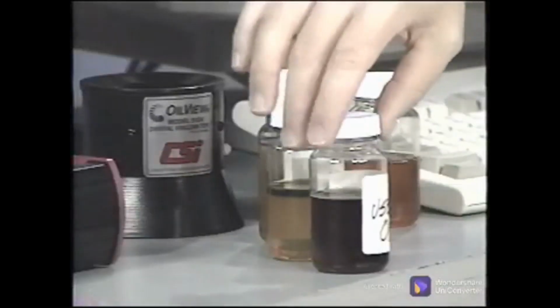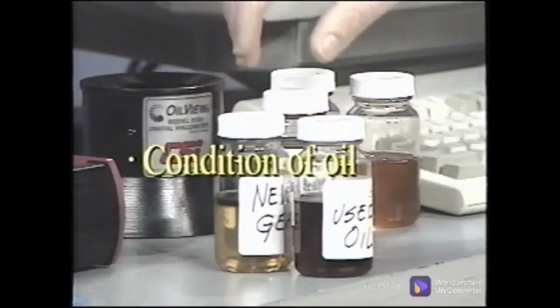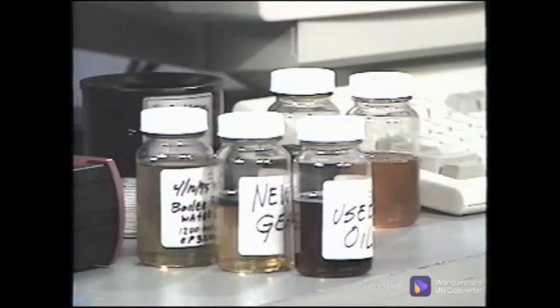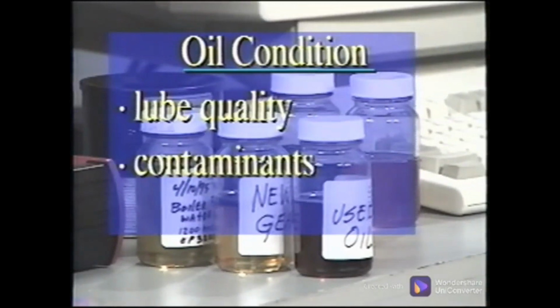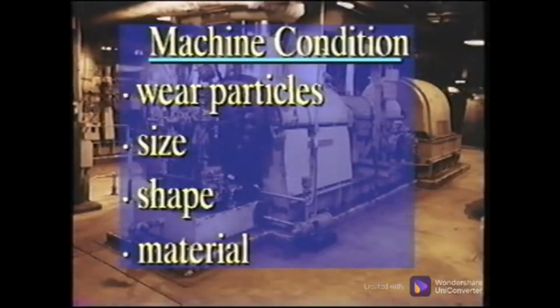There are two categories of information testing provides. One is about the condition of the oil itself, and one is about the condition of the machine. For the oil, you want to know the lube quality, including the condition of any additive package, if there are any contaminants, and whether it is the correct oil for the particular application. The machine condition is determined by examining the wear particles for size, shape, and the materials such as ferrous and non-ferrous metals.